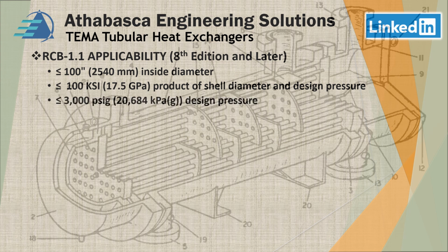They also say that it's applicable only if the pressure is not greater than 3000 psig design pressure. They say the maximum shell thickness must be less than 3 inches. And the stud diameter must be less than 4 inches.